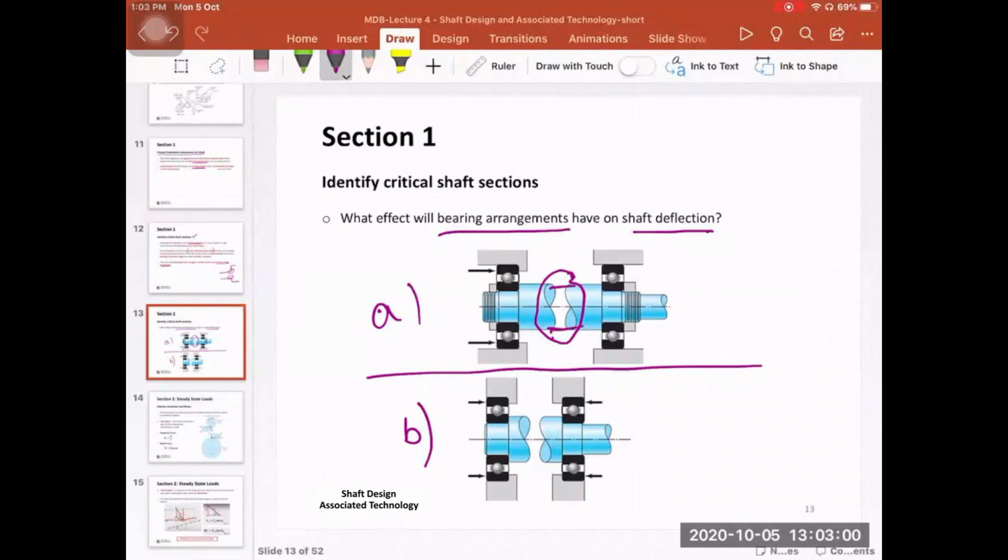On the left-hand side, you see some arrows. It means that in this direction, the shaft and the bearings can take the axial reaction. So if the force is pushing this to the right-hand side, it does not move, right? But here you have flat surfaces, which means that it is free to move to the left and to the right, okay?